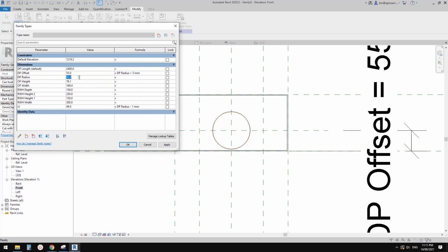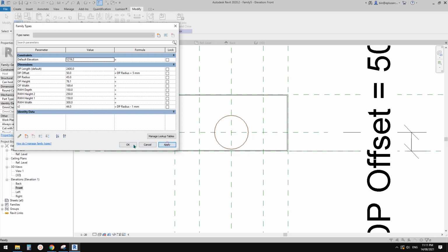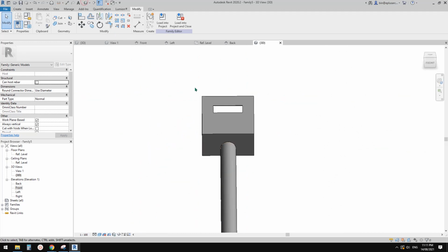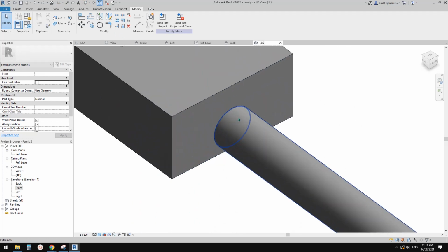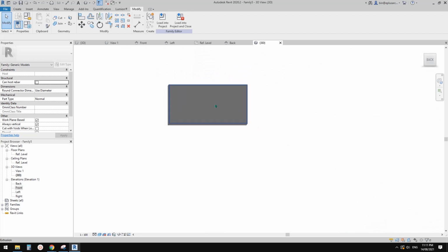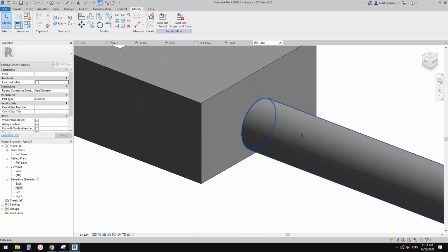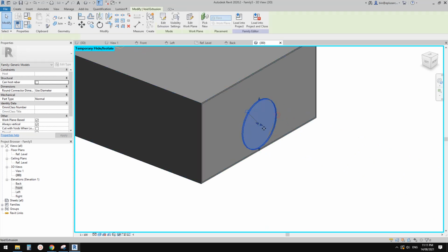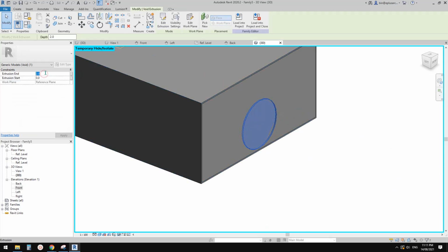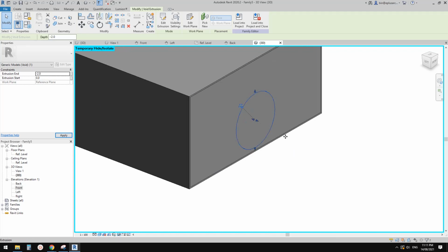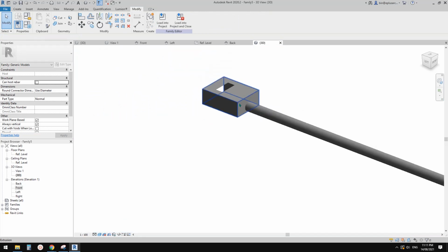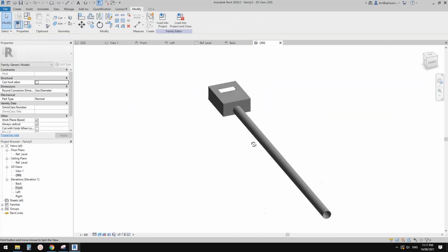So okay, yeah, I'm not quite sure how. There might be some standard there. So yeah, if I am wrong, please let me know. Okay, so the void, it's not cutting there. That's okay. Let's just select this. It looks like it goes in the wrong direction, so we just type in -2 and it will cut a hole here.